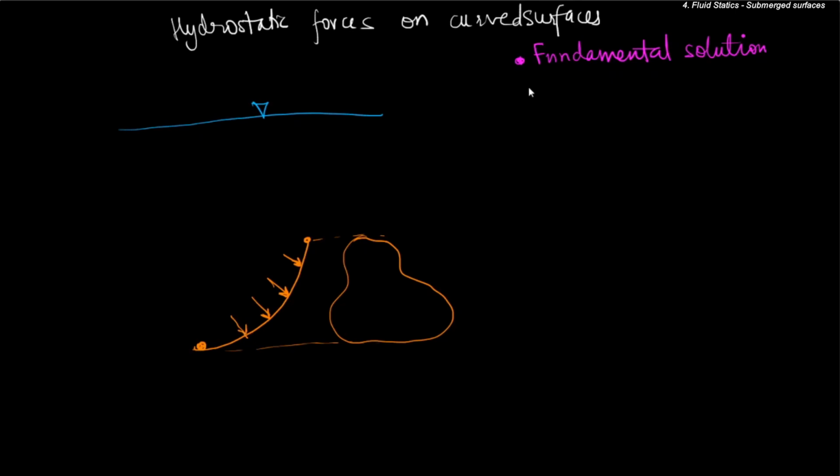So using that, we know what the normal direction is, and we can parameterize the curve. So if this is ds, or rather let this be dA, the differential force would be equal to integral p dA n cap, but it will not be n cap, it will be minus n cap, because the force due to pressure is compressive.